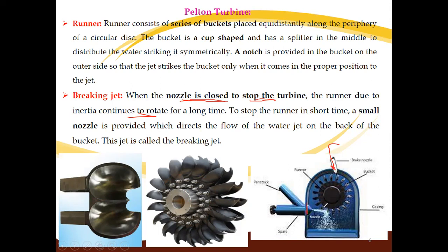So to stop the turbine in a short time, a small nozzle is provided which directs a water jet onto the back of the bucket.